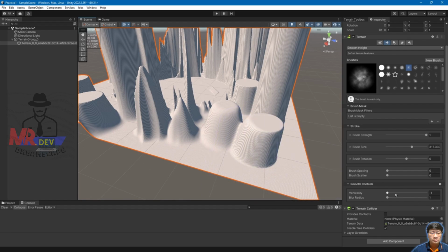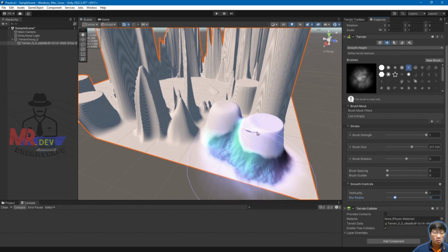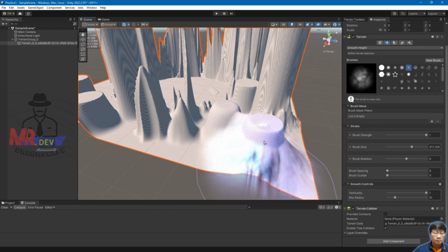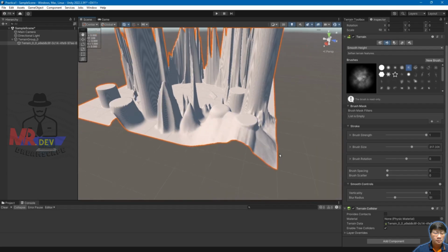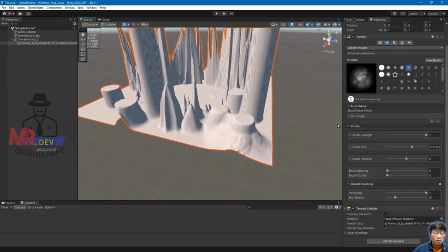And if we make it a positive smoothing, what it does is from below this surface of 0 it is going to push upwards. So that's what it's for, and the radius would be how much around us we want to soften. For example, I can increase the radius there, and when softening, look, it considers more. Okay, then that would be the height smoothing.